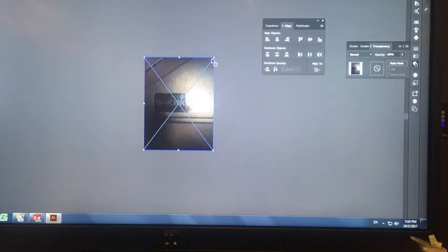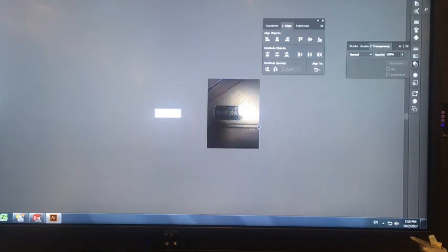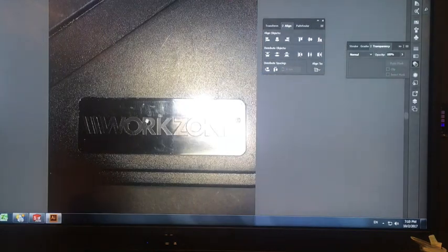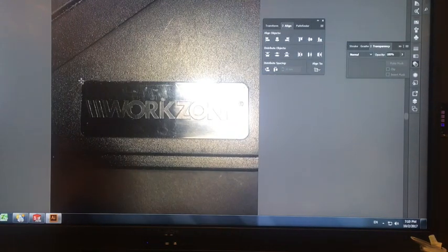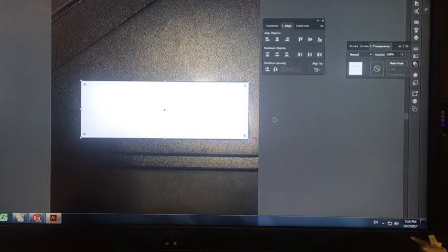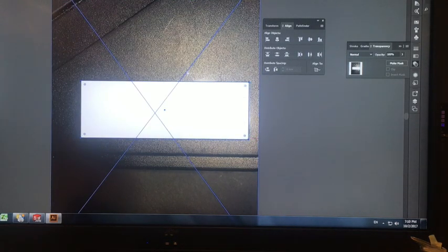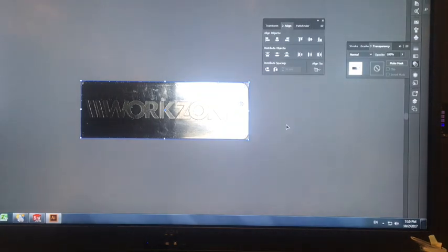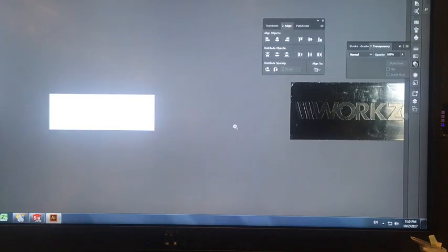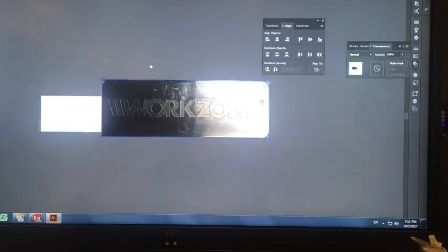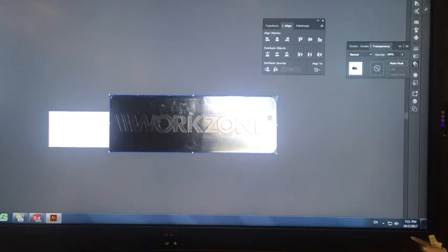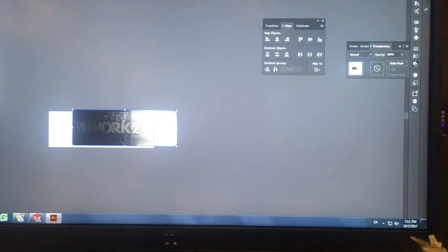And so then I can just grab this, and here's another trick. If I draw a box over this shape and select them both and go Control Z, it's going to crop it. So then I can select that and actually put in the dimensions. So I might put in just the width 70 and the height 23. So I was pretty close with my guess. And align that.